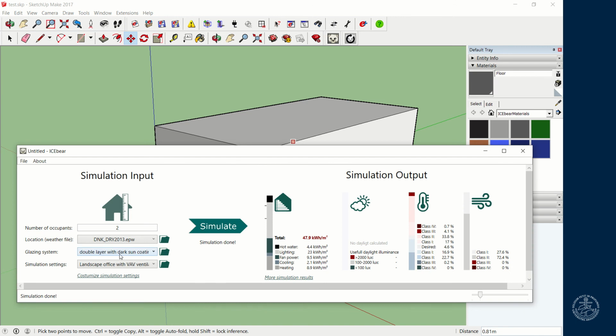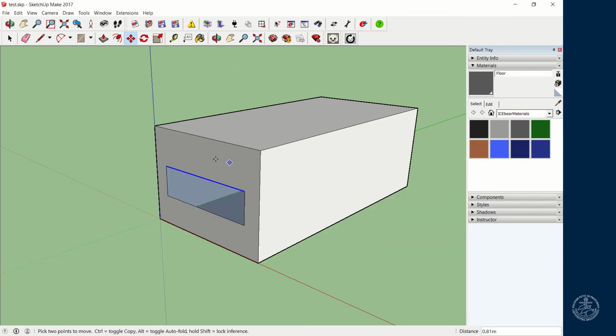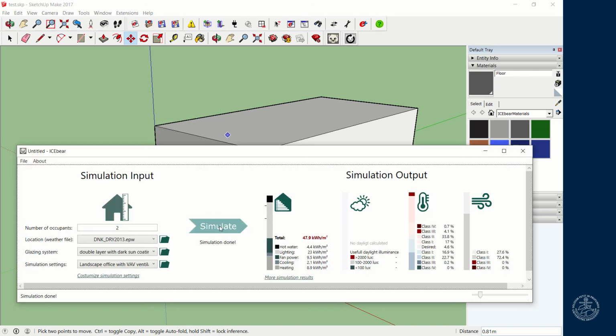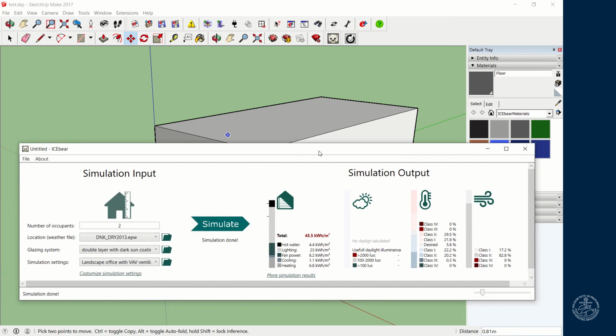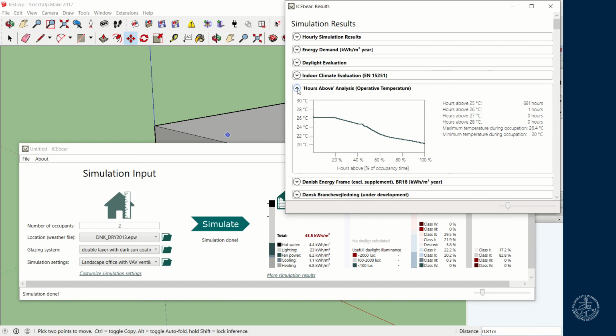And then we can go into ICEbear again, and hopefully you will see, yes, now the fenestration has changed to a smaller area of 2.98. And that's also if you choose to change whatever geometry, you have to remember, please, to press the update, and then you can do the simulation again, and we can just try to see what happens when we made a smaller glazing here. I completely eliminated the overheating issue. You could have other issues with this building design, but at least in terms of the overheating, it seems quite reasonable now for many purposes.